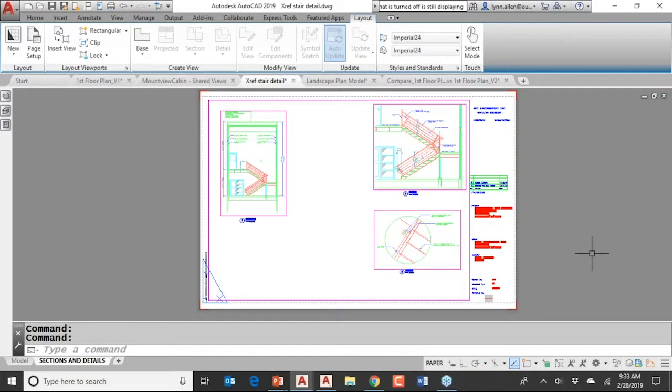Well, you know the answer to that. That is because not all those layers were set to ByLayer. What? Oh, how frustrating. That's okay. I'm going to show you a way to fix it. There is a system variable called XREFOVERRIDE, and this is not just 2019. This is in previous releases as well. So for those of you who haven't upgraded yet, still write this down.